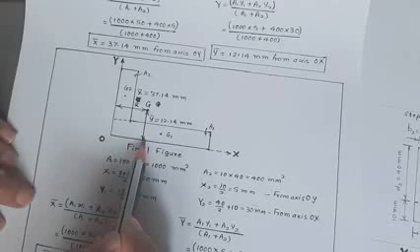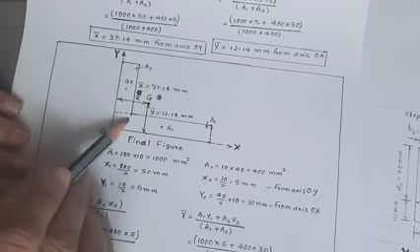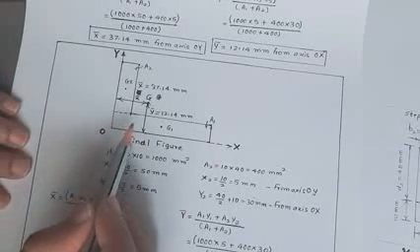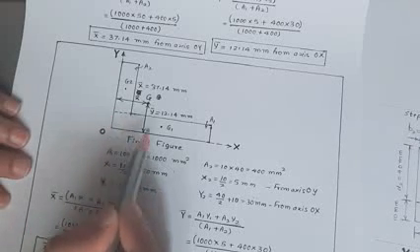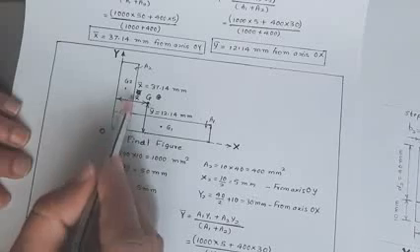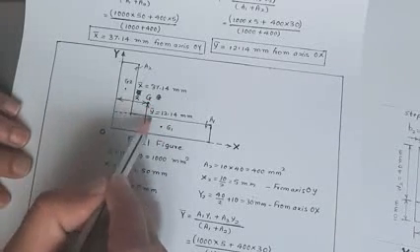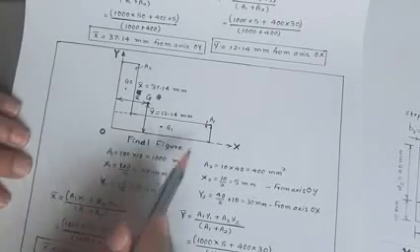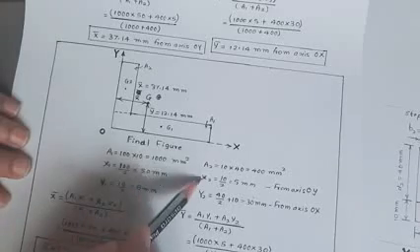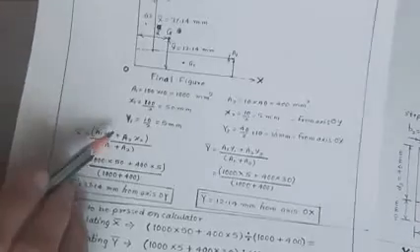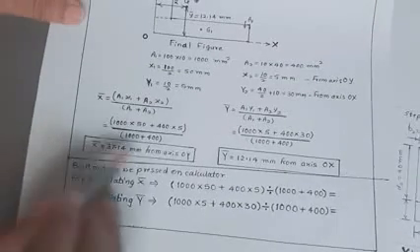Now in the exam, you should draw only this figure. What is important to remember is this dotted line. You must show where you have split the areas, then the reference lines OX, OY, G1, G2, and the centroid G, x bar and y bar. This much is sufficient in the exam. Then write the areas A1, x1 and y1, A2, x2, y2. Write the formulas for x bar, y bar, substitute the values, and then write the answer, highlight the answer and write it very clearly.